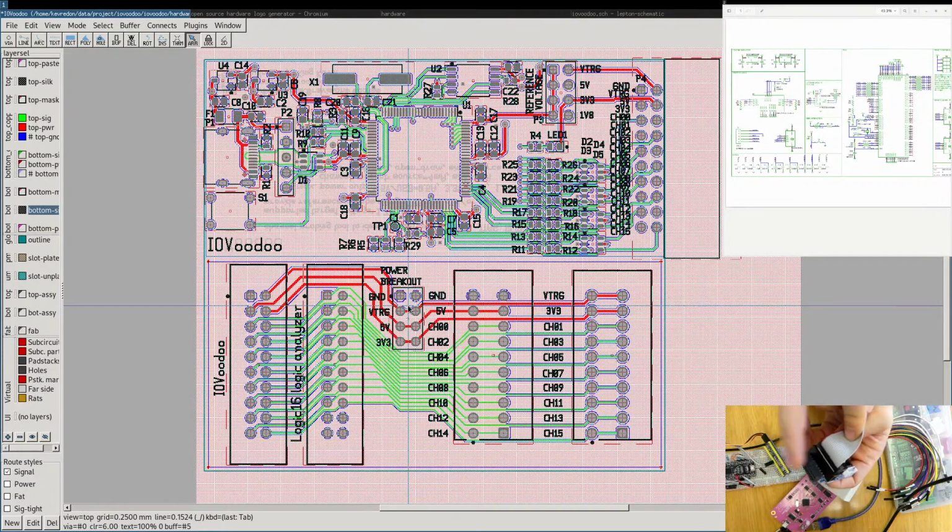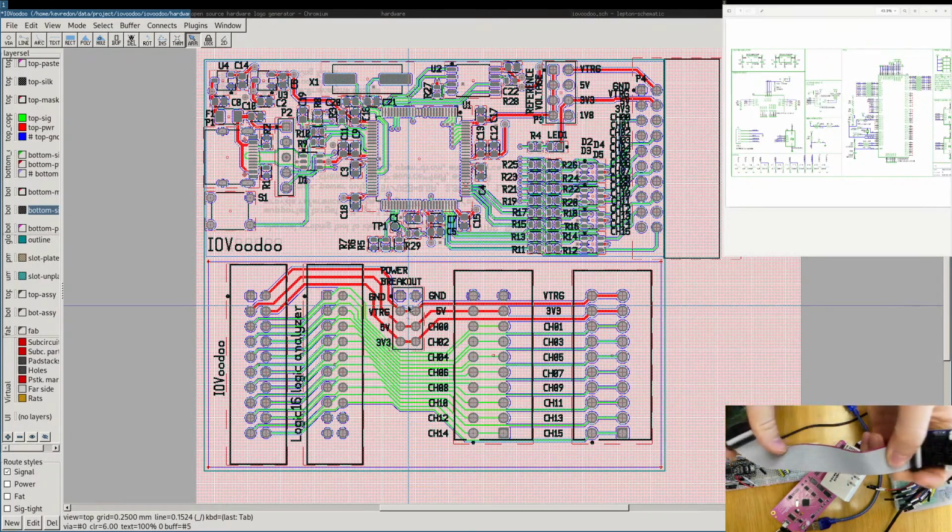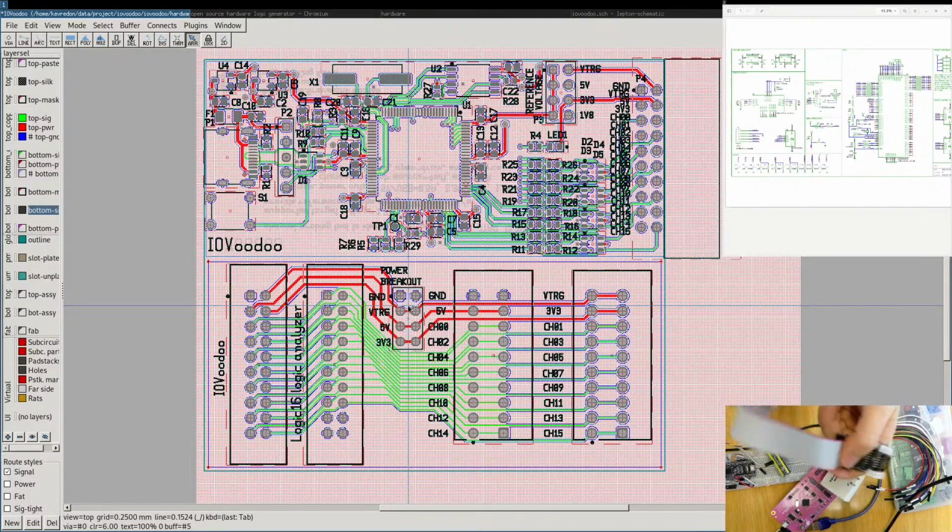Or you connect directly using this thing, and then you break out with many other connections, because this is the ARM format, but you have plenty of other ways to connect JTAG. And actually I could also add this connector to my design, but I don't think it is really necessary. If I have the breakout board, I will use these ribbon cables to put it next to the target. So yeah, I will not put this connector.